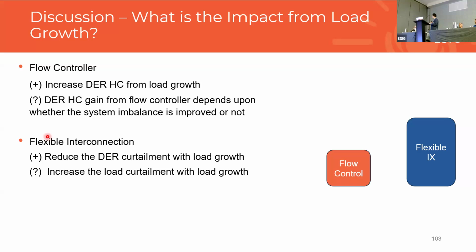Yeah, that's right. That gets back to what we were talking about, whether it's single phase or three phase, and the types of voltage control that are also allowed. If voltage control is not allowed at all, you're going to pull your phases together, which can open up a little bit of bandwidth. But it can also optimize the voltage control of the DER itself, so you can get a little more benefit out of it, in that unconstrained region in the operating envelope plus the voltage controlled region.